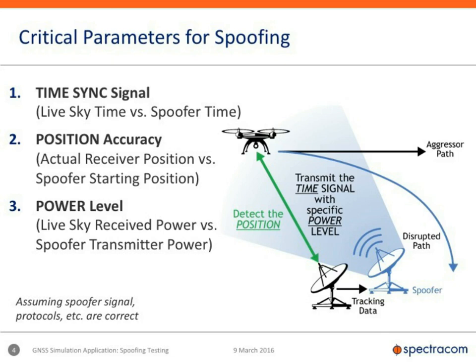So the whole issue here is about capturing the receiver. You're either trying to capture the receiver in its signal decoding or somewhere in its navigation solution. So what the spoofer has to do is enter into that capture range of the receiver, first get the receiver to lock on the fake signal, and then pull it off. So let's start with each one of these.